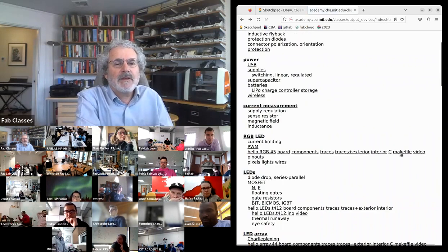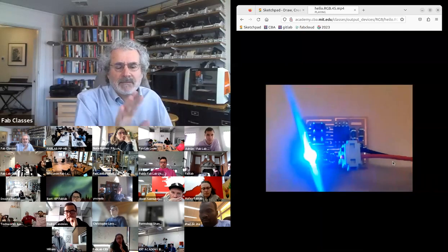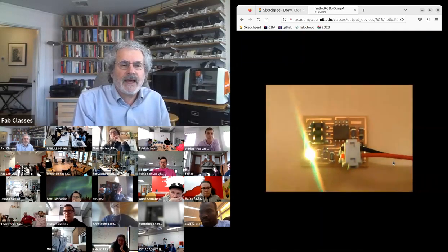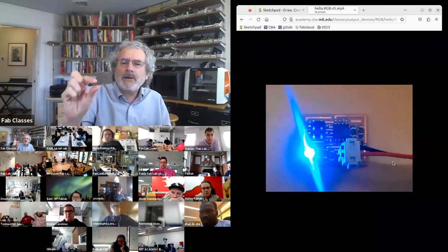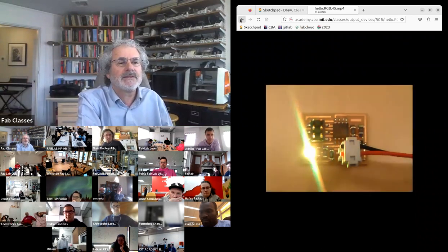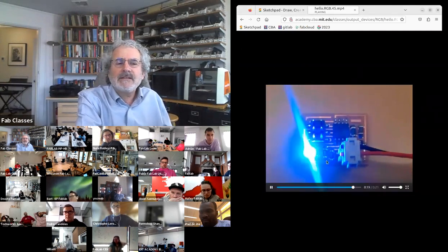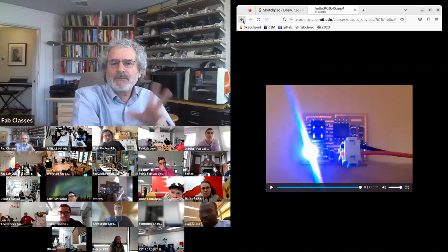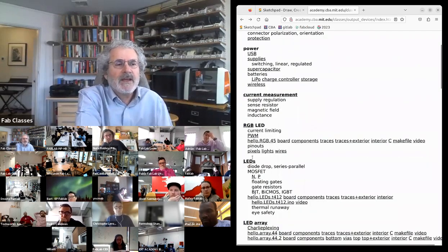And so that takes me through the red, green, blue, but by using those, I can continuously vary the color of the LED and the brightness of it. And this is in fact 1 pixel of what's used in the giant jumbo displays. You do need to be cautious. These RGB LEDs, many of them look the same, but have completely different pinouts. So you need to check the pinout for the one you're using.